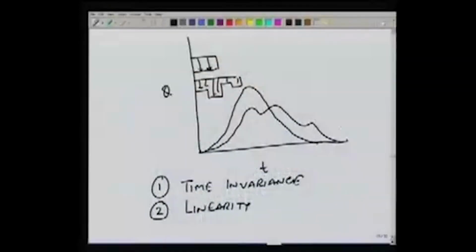So not even catchment to catchment, but even from event to event, one rainfall to other rainfall event, the hydrograph will be different. So it's very difficult to theoretically analyze this unless we make some assumptions. So these two assumptions, time invariance and linearity, help us analyze the hydrograph and estimate what would be the runoff for a very complex rain.